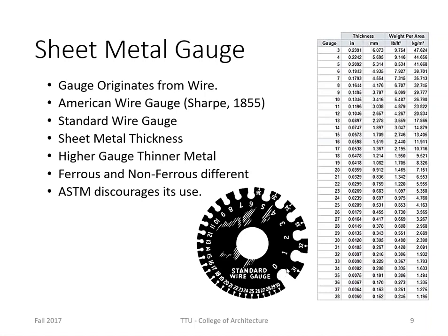In standard wire gauge, you can go down to what is called 0, and then all the way up to 30. In American wire gauge, I was wrong. This is the American wire gauge. What I want you to notice, and it's counterintuitive, is that the smaller the gauge, the thicker the material.